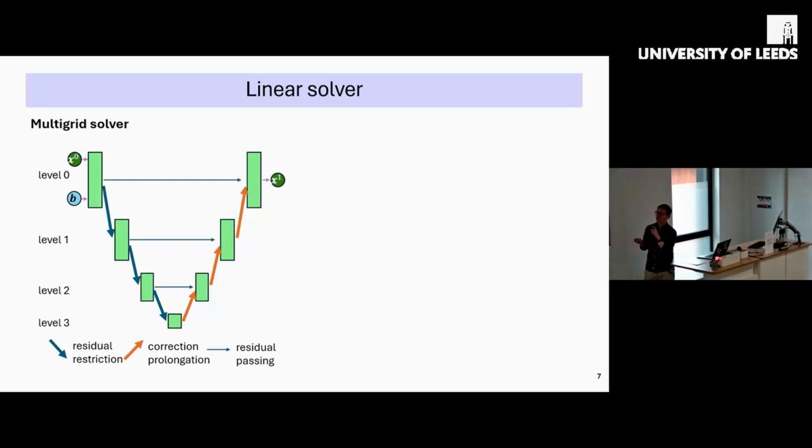So a multigrid solver uses different levels of coarse mesh to agglomerate your nodes together, so that you get a coarse mesh, and those errors on a fine mesh become high frequency errors on the coarse mesh, so that on each of these multigrid levels, you tackle different frequencies in your error, so that you get an efficient solver.